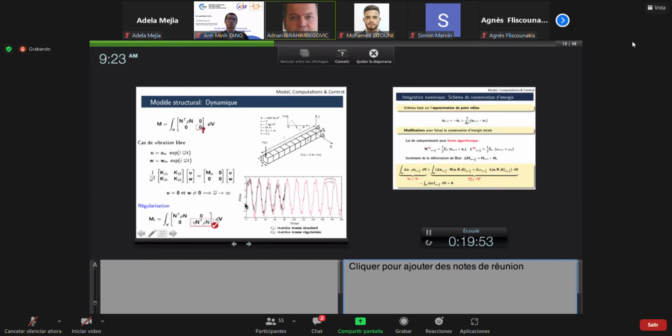So here are some of these examples. One point is, for this extra rotation degrees of freedom, mass is not really represented. So if you have a mass with a 0 term, it could be really dangerous, because a 0 term in mass means infinite frequencies. The presence of the infinite frequencies computationally could definitely be very dangerous.